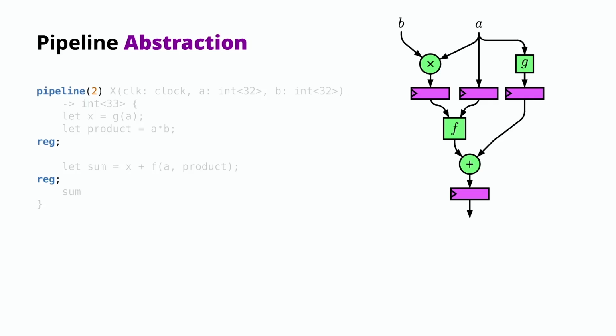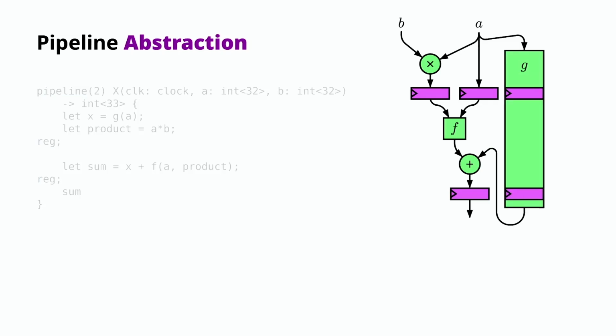Let's say we build this and then we realize that the G block over there at the top right is not good enough. It is perhaps running too slow, so we need to pipeline it, or perhaps the requirements change, so we need to do more in the G block. Whatever the reason, we change G to accommodate these new changes, and now we've refactored part of the code, and we're going to be affected, because the change looks like this graphically. And if you look at this graphically, you can see that this will not behave as it did before. My sort of controversial opinion about this is you should never have to look at a graphical view of your circuit to figure out if it will work correctly.